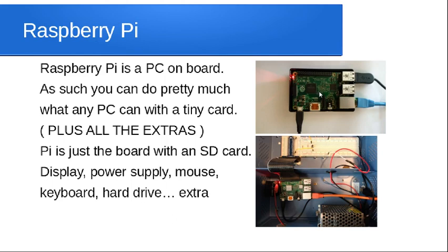You've got built-in Wi-Fi in version 3. You don't have to do anything there. The operating system is on an SD card. You're going to get an SD card. You've got to basically download some free software from Raspberry Pi, load it up, format it, and stick it in. A little Raspberry Pi, you'll see where about the symbol is underneath there, and then you're ready to go. You're off and running. Not too overly complex, but it takes a little bit of getting used to.